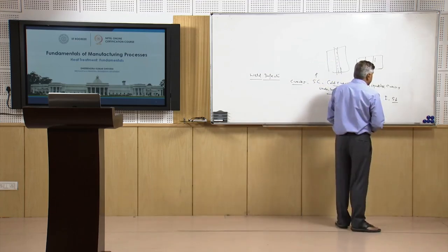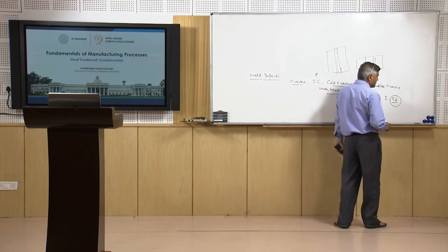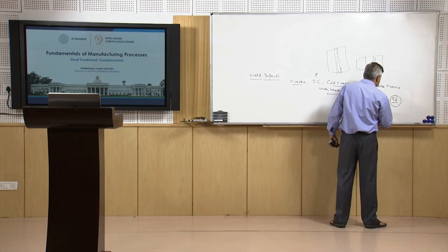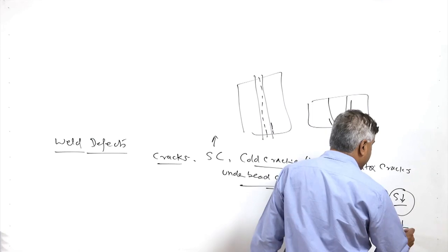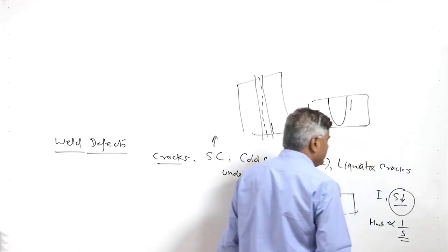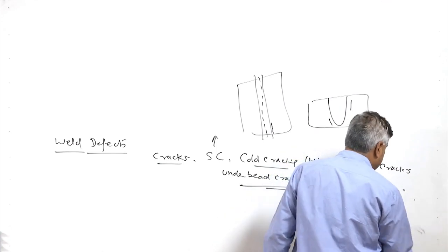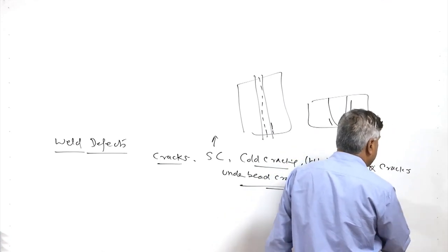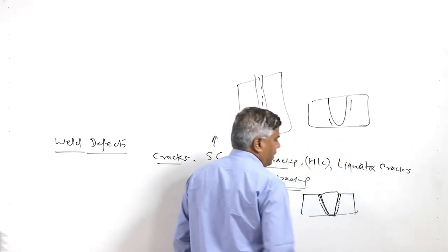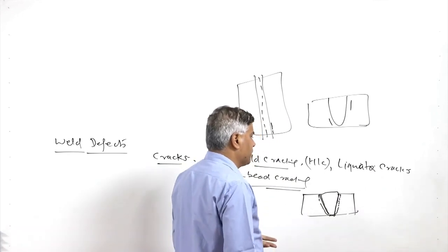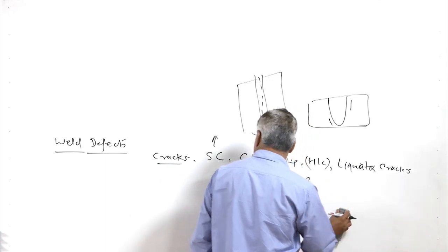Whatever the source of heat used for the fusion purpose, its speed is reduced so that the net heat input can be increased, because heat input is normally inversely proportional to the speed. The higher the speed, the lesser the heat input. So increasing the heat being generated through suitable control of the process parameters, or reducing the speed, helps in overcoming the issue related